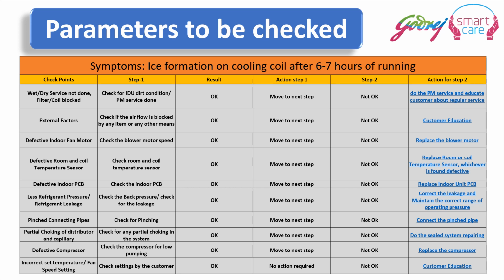Check for the compressor defect, check for the compressor's low pumping. If it is there, we have to replace the compressor. We check for incorrect set temperature or fan speed setting by the customer. If it is not okay, we have to educate the customer.